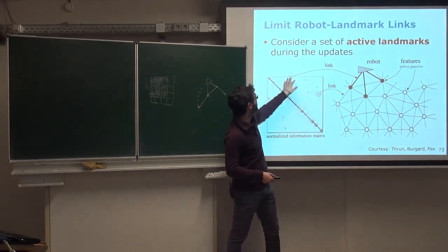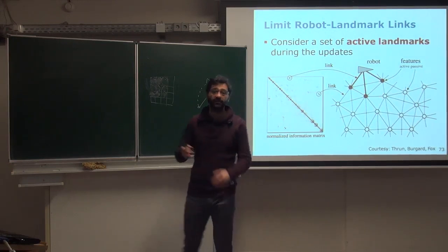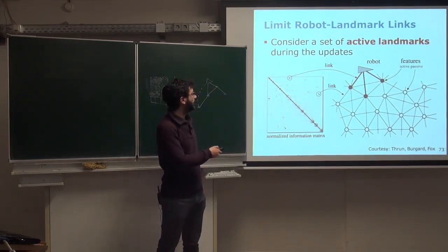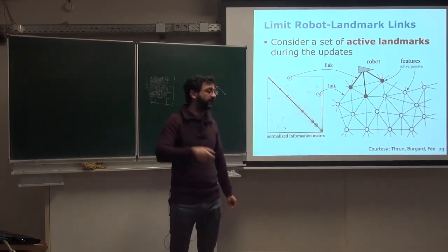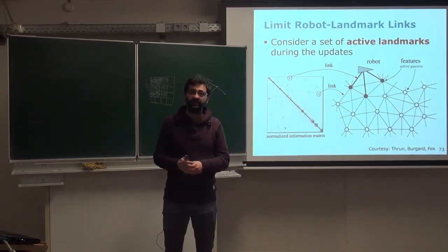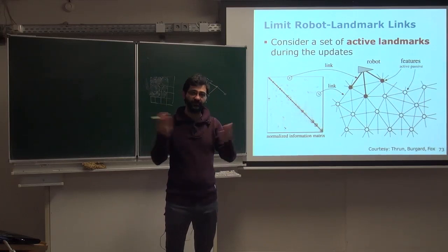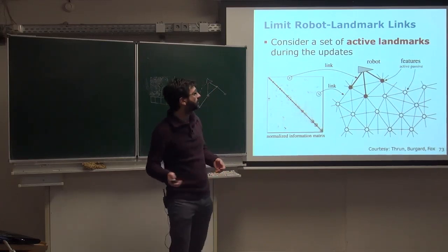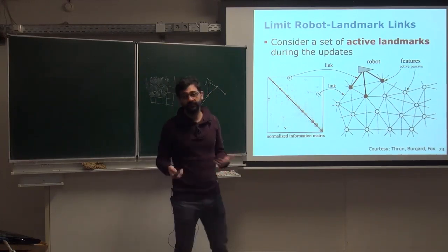So this is still kept, but what we do is that after the robot moves on, we somehow cut some of these active landmarks, so we put the zeros in, well, we don't really put directly the zeros. There is a way of computing a new information matrix that actually models the approximation that we do, and it turns out that we are just cutting things there, and we'll see later on what that means. And then we get this new distribution.